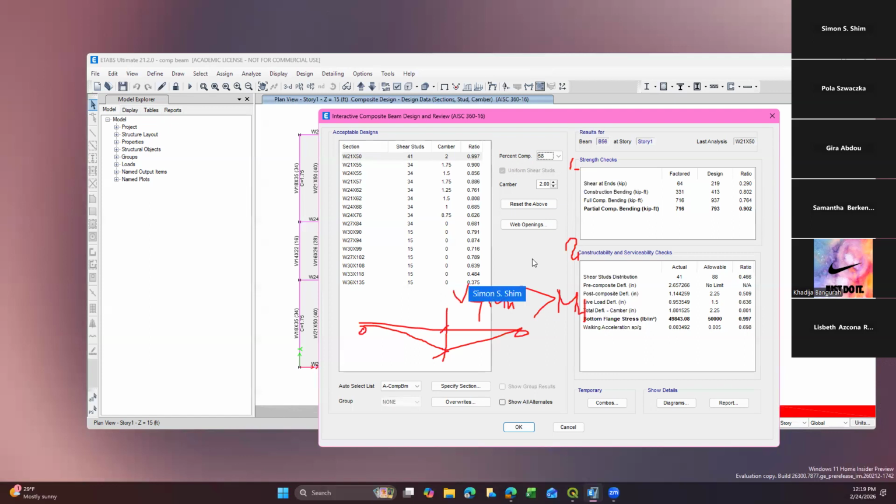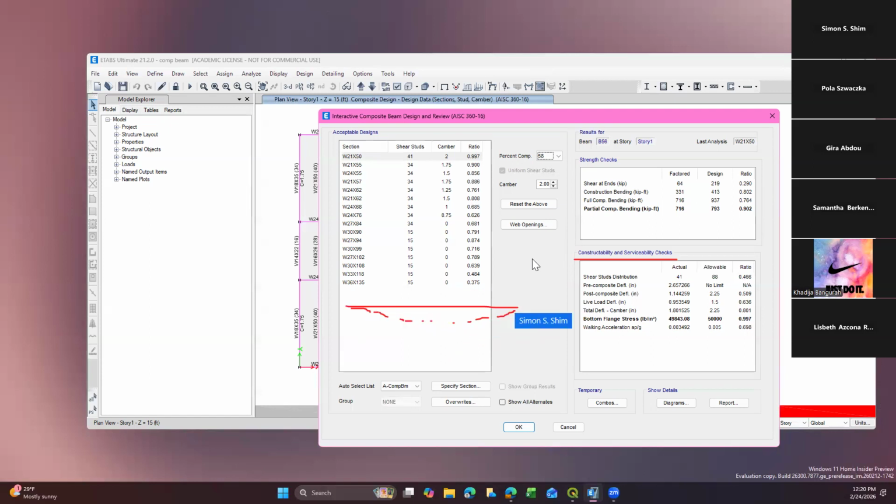That's the philosophy, which is safety. It's common sense. Now, deflection is not strength governing. If the beam deflects too much, obviously the function of this slab is going to be a nightmare because anything is going to roll down. It could be a trip hazard, and it doesn't do its proper function.